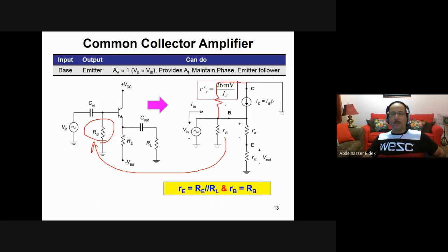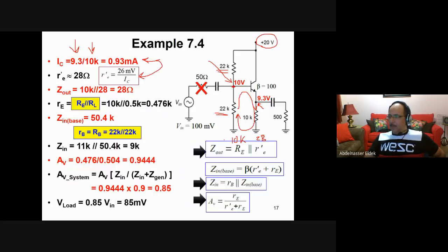So these two resistors will be parallel to each other. Why? Because the source, the VCC, will be grounded, connected to the ground. Then the one on the top will be parallel with the one on the bottom. Then this will be little RP. So you have a resistor here. So this one parallel with this one will give you RP. So now let's go back to the example. So you have 22 parallel with 22. Then of course this is just 11K. So this RP is 11K.